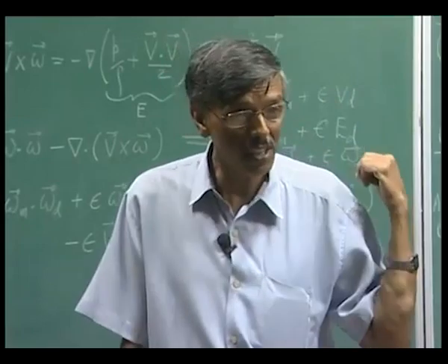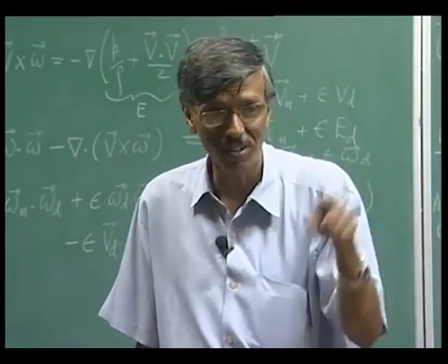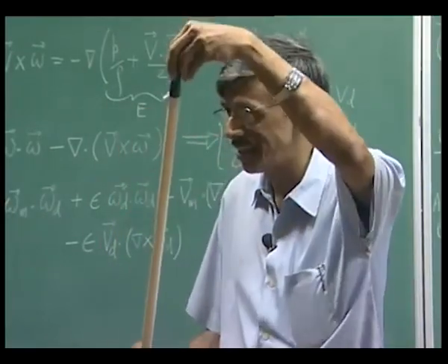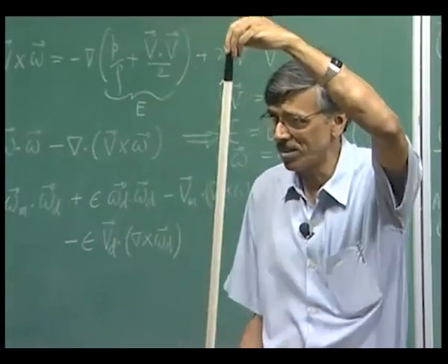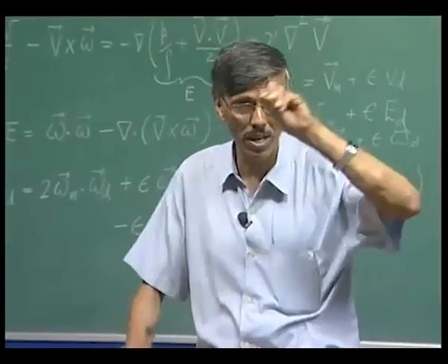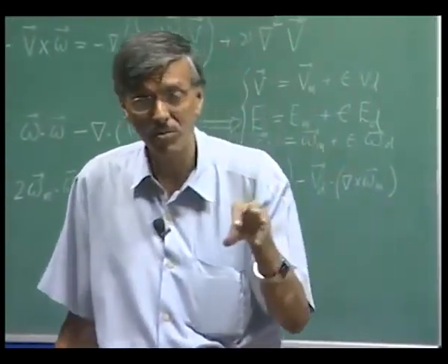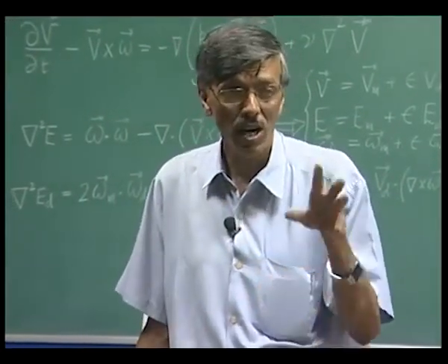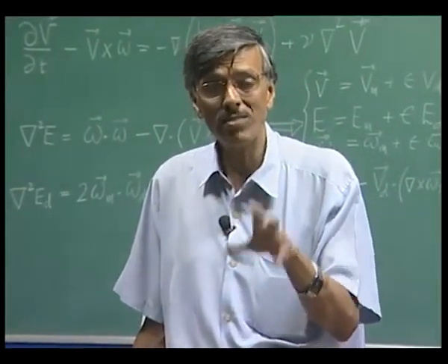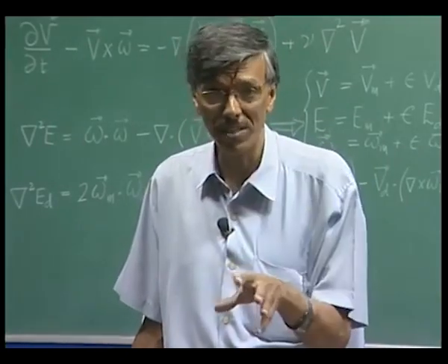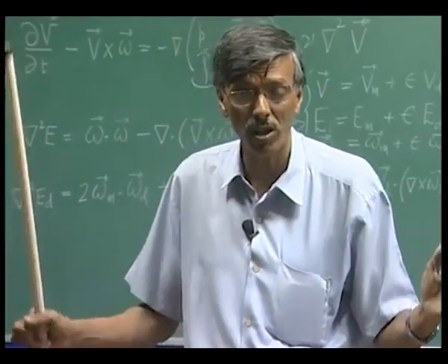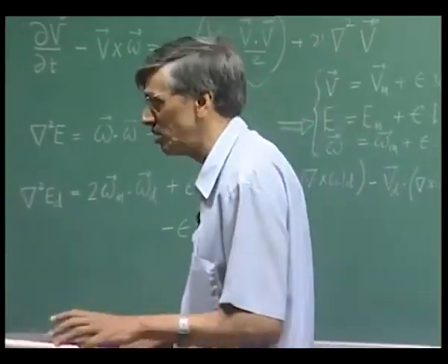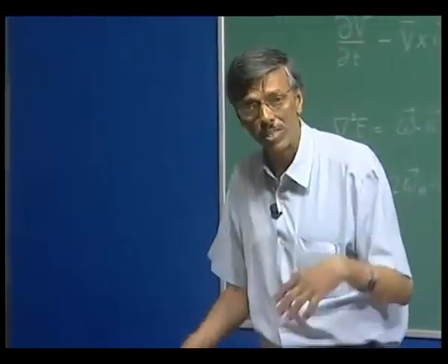That is where we saw Kendall's experiment, where he rotated those two cylinders at the end of a pivot, and those were ejecting vortices at a fixed frequency, and there you could see a signature of a TS wave like scenario. So, what do you see there? You saw there TS wave packets, but in general you do not expect that.